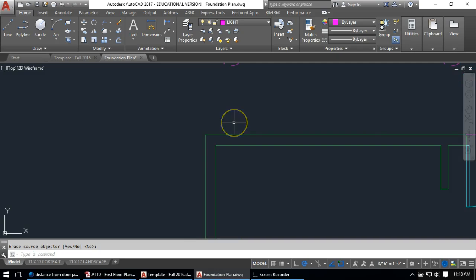This one's 6'4". So I'm going to offset, that's the center line, 6'4" right over. And there's actually 3 windows at 1'6", which means I've got 1 3-foot clear plus another half, which is 1'6". So that's 4'6" I can offset. If you didn't want to do the math, you could just draw out the windows and move them into place and find it. Also works. But if you don't mind doing the math, just do the math and get it done.